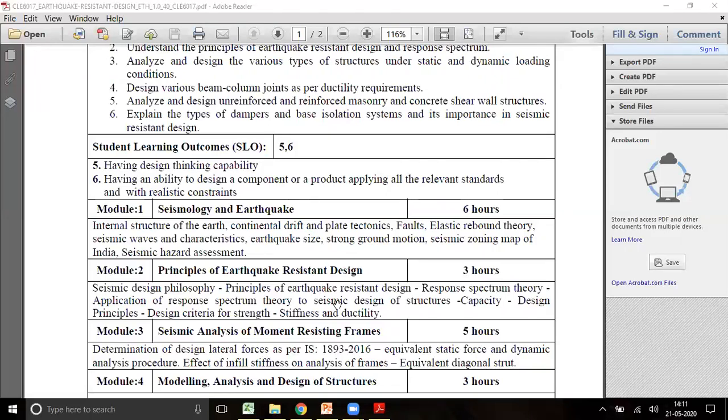Okay. So in a building, if you design based on the column being very strong and the beam being weak, then it will be good. It will survive for a long time. In reverse, the beam is strong and the column is weak. If we design in such cases and the column fails, definitely the entire collapse of the structure will occur. So to avoid that, we prefer strong column weak beam criteria. Okay, so in order to achieve the strong column weak beam criteria, there are certain design rules and recommendations